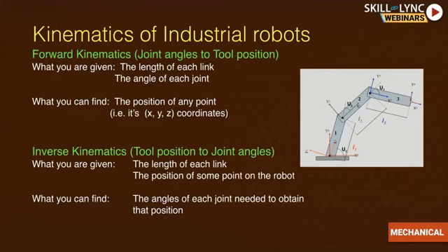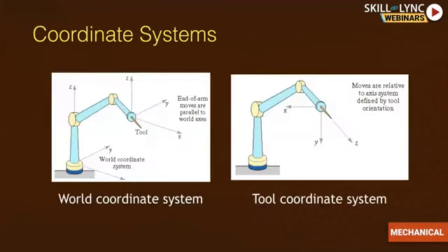Each joint is going to have a frame, which is linked to the adjacent link. So you do some transformation from the first frame until you reach the last frame. The last frame is called the tool frame, or the tool coordinate system. And the first one, which is there in the base, is mostly called the world coordinate system. In between, each link is going to have its own coordinate system. Coordinate systems can also be called a frame.